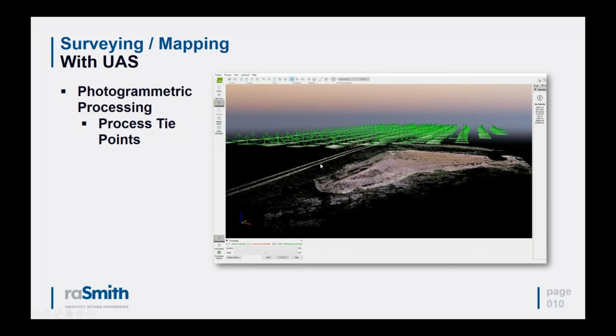And this data underneath that you see below there in this triangular shaped land pattern are all of those tie points, literally millions of tie points for this site. Those tie points ultimately form the foundation for the deliverables that come out of the back end of this process, which can include things like point cloud data or digital terrain models or even orthomosaics.